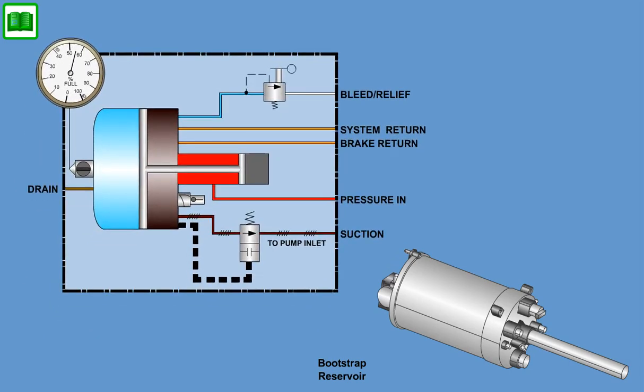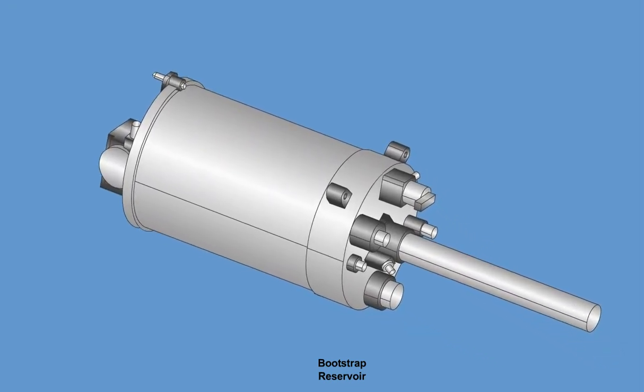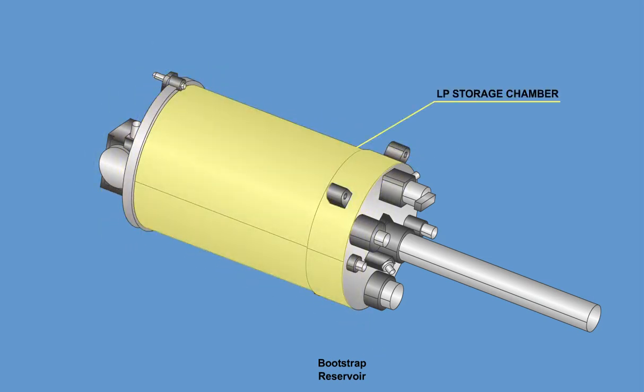The reservoir provides the necessary fluid volume demanded by the hydraulic system, including pressurization of the pump inlet. Changes in fluid volume due to thermal expansion and contraction, system leakage, and differential area of the user actuators have been taken into account in sizing the volume of each reservoir. The major components of the reservoir assembly are low-pressure storage chamber,